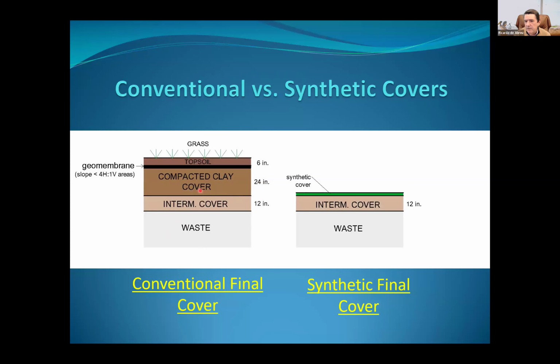Then after you're done with that location, disposing that location, you install your final cover system. What is the final cover system? It is the compact clay cover. And these numbers, this thickness, may vary depending on the location. This is typical here in Louisiana, United States.